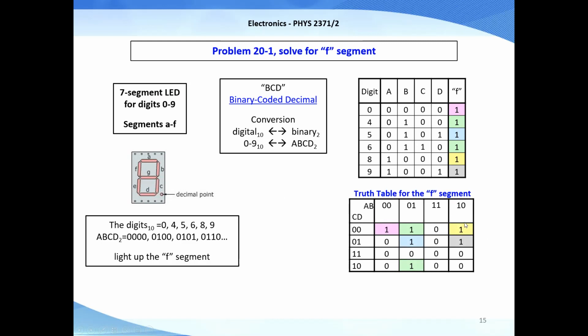So you approach this as, well, here's 2 that are adjacent, and here's 2 that are adjacent, and here's 2 that are adjacent. If you take these 2 that are adjacent, you can see that it doesn't matter what D is, D can be 0 or 1, so D is going to drop out. You can take these 2, and you can see that it doesn't matter what B is, B can be 0 or 1, so B can drop out.